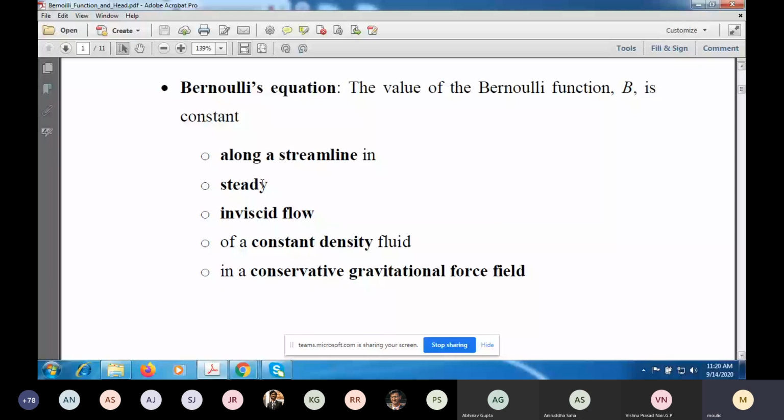Now this point about whether the flow is steady or not actually may depend on the frame of reference that you choose in the analysis. If you recall, in the previous class, I showed you a figure of a bucket of the Pelton wheel which was translating, and I had used two reference frames. One was a stationary frame, the other was attached to the moving bucket.